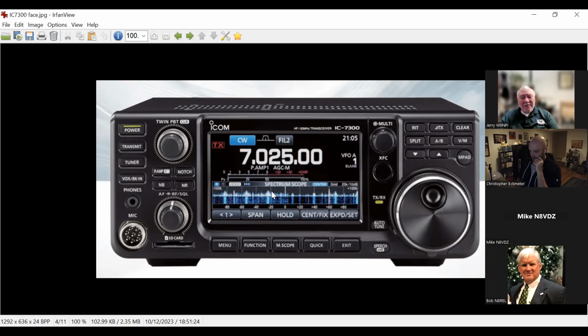If there is a carrier signal, like on the 40-meter band, especially up in the voice area, we share that with international broadcast stations. So if there's a carrier signal that's going on and on and on, you can use a notch, which will phase that out.